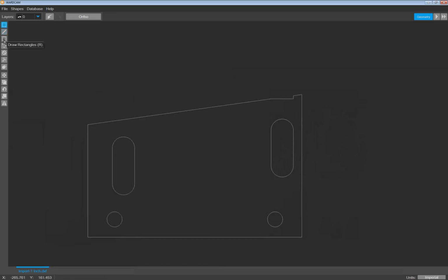And you see we have a rectangle box here. I'll talk about that one some more later. You've got options to draw points. Sometimes maybe you might just want to do a pierce in a certain location on a part because you're going to drill it out later, because maybe it's too tight of a tolerance, too tight to waterjet cut. You can use this point command and you can draw a point at things like centers of circles and such, and then we can pick up on those points later to add different tool paths to those things.